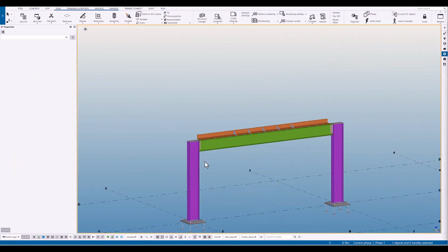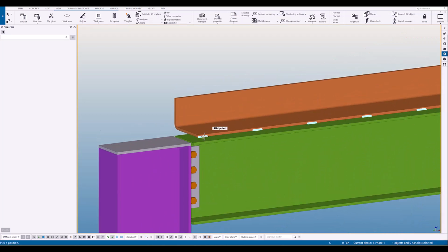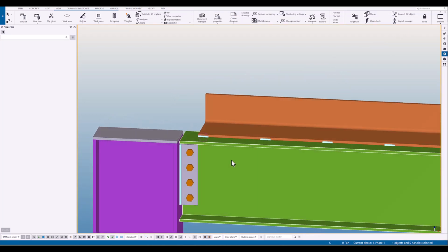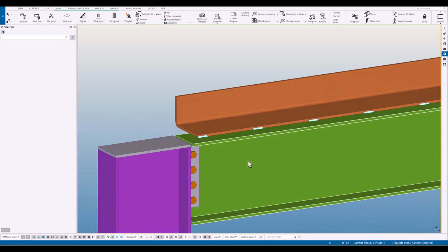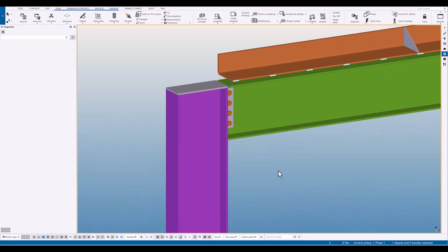Now that we have gone over adding basic welds to the model, we can talk about polygon welds. A polygon weld is essentially a weld that follows a polyline. This is especially useful in instances where a weld on 3 sides is required. Maybe a weld return is called for by the engineer, or maybe even a specific length of weld at specific locations are required.